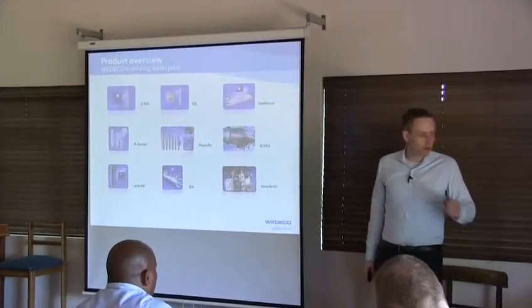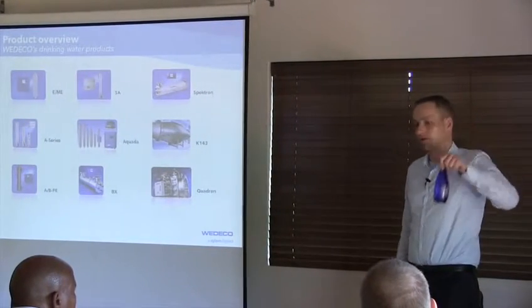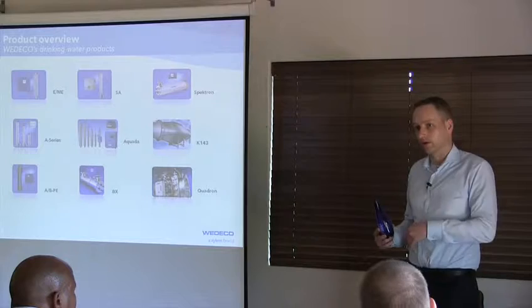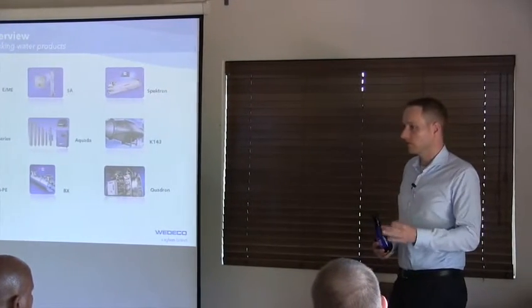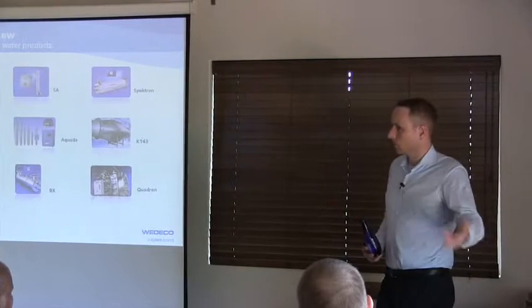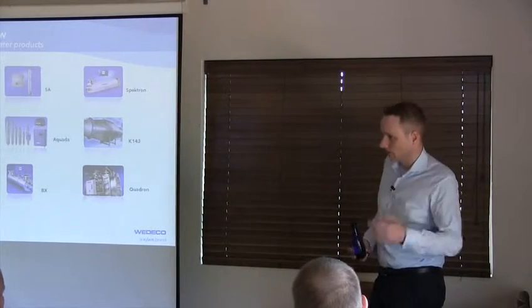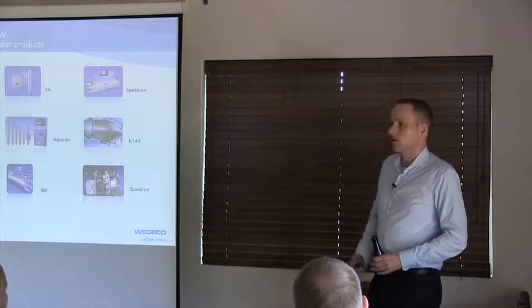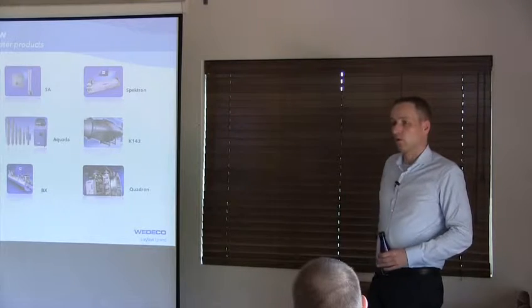I have seen a water sample that was as clear as the water in this bottle and had a UVT of 30% due to the chemical compounds in the water. So you cannot see UVT really. Mostly you can; in most cases the water is brown or yellowish, so you can have an idea. But I also saw crystal clear water samples which had a very, very low UVT.